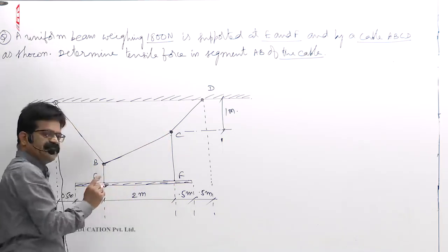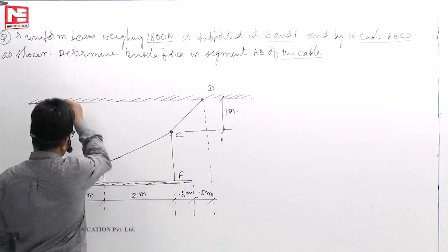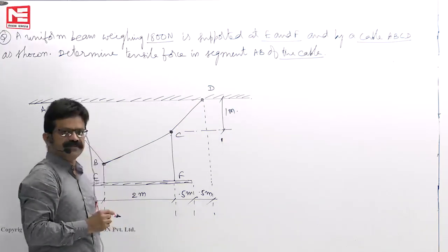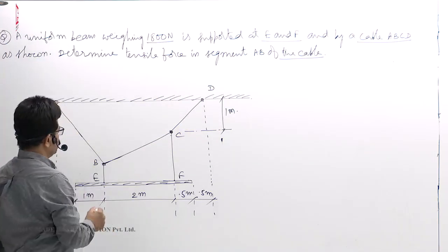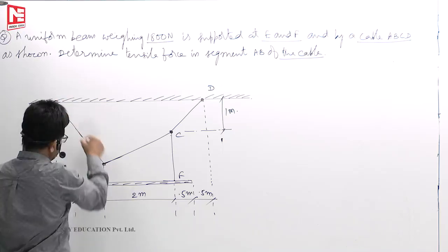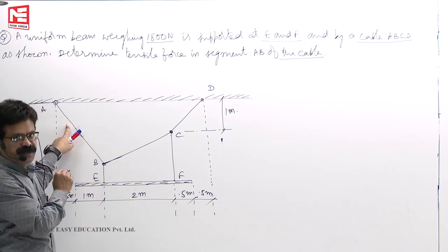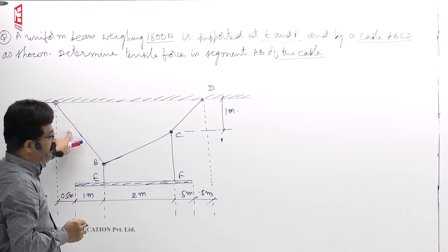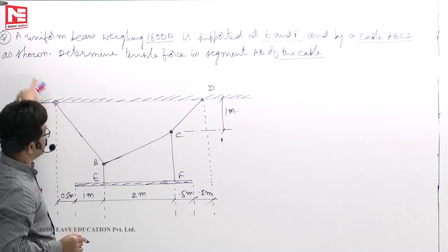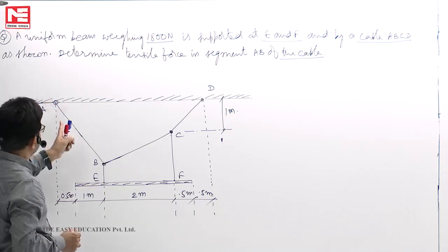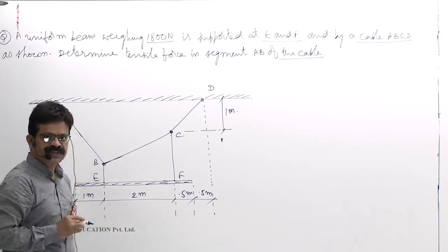CE, BE are two independent cables and they are hanging on to the cable ABCD. So the cable took this much shape. Now he is asking what is the tension in the cable AB. As in the earlier problem, if you want to find tension in the cable AB, you must know the reaction. If I know the resultant reaction at A, then whatever RA is there, AB is also the same. That idea first we should get.